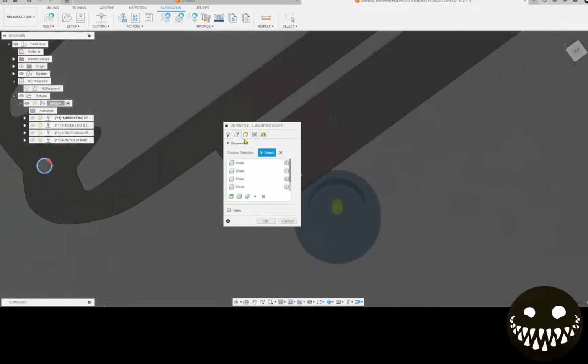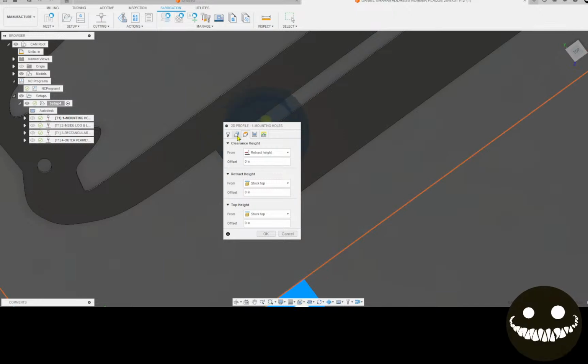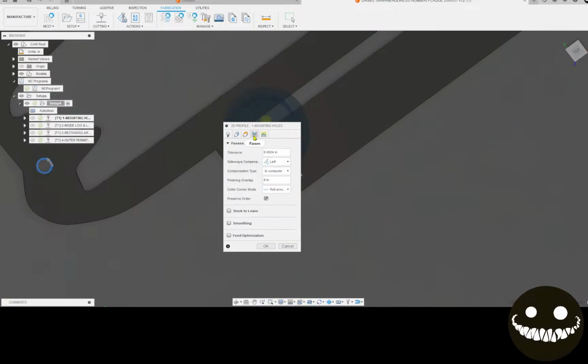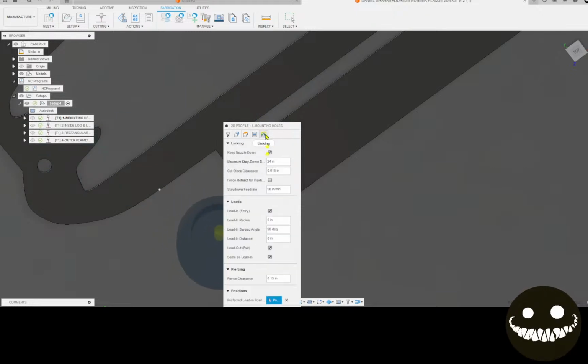Yeah, let's see what else we have going on in here. Wire cutting to the left, good. You could always take the tolerance down. I don't think it would matter. You've got pretty clean geometry here. Let's not complicate it. And I'm not going to mess with your OG settings up here, because I have a torch height control.